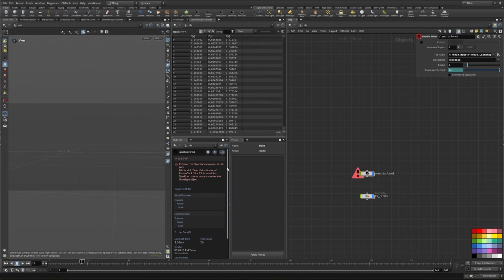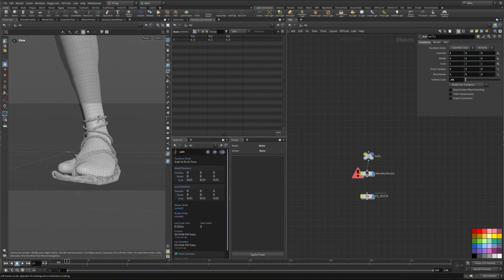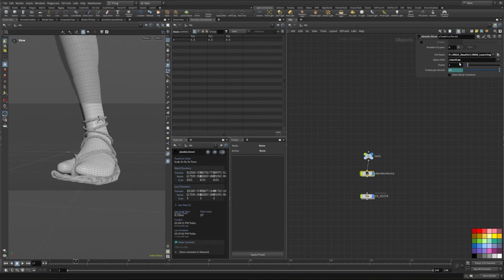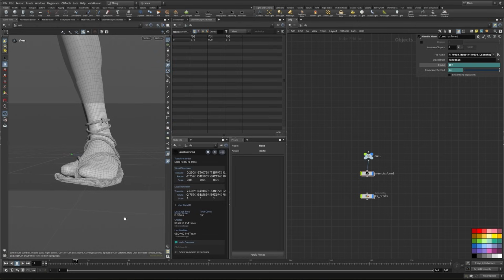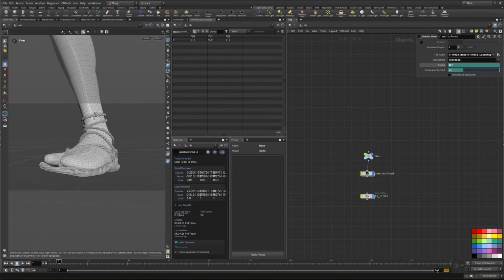Now it's really far away, because we also have to scale it down. And for this, we're using a null. And we scale it down with a 0.01 maybe, like this. This is great. But still the animation is missing of the camera. And also make sure the C of the shotcam here is a big C, so it's also working. And in the frame tab, we type $FF for the frame number. So each frame the camera is animated, like so. And also here, where my 240 is, I will type 100. So my timeline is only 100 frames long.